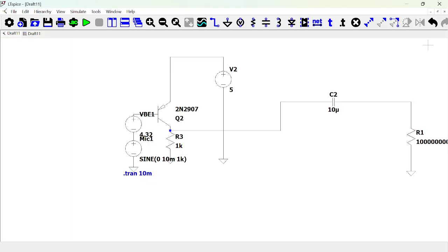So why is it acting like a proper circuit now? Because now the base, which is N type, is more negative than the emitter, which is P type. So the emitter is more positive, and the difference between them is 0.68, and we have a current of 2.57 milliamperes flowing through them. So at least we have an idea on how to use the PNP as a common emitter stage for an amplifier, giving us a bit of comfortability or familiarity with the PNP device.